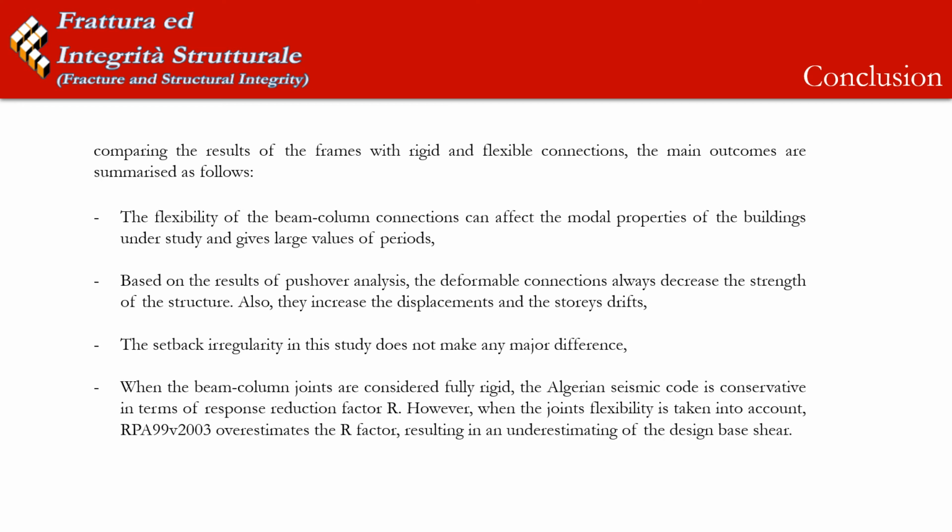When the beam column joints are considered fully rigid, the Algerian seismic code is conservative in terms of response reduction factor R. However, when the joint flexibility is taken into account, RPA overestimates the R factor, resulting in underestimating the design base shear.